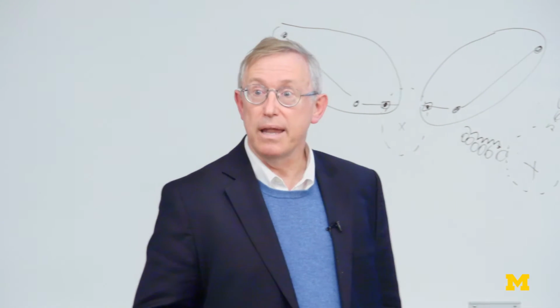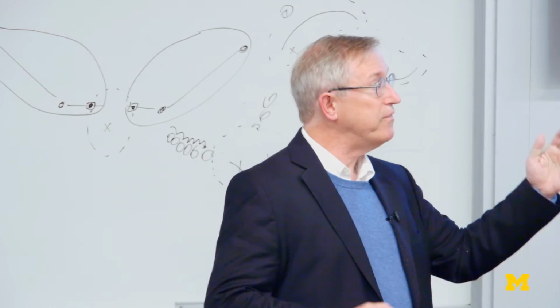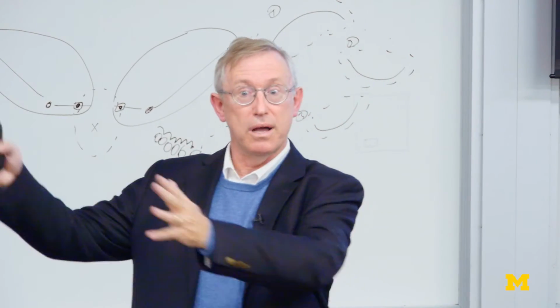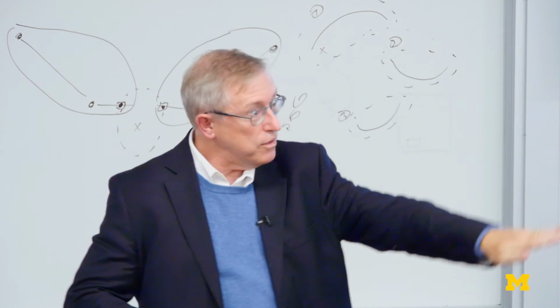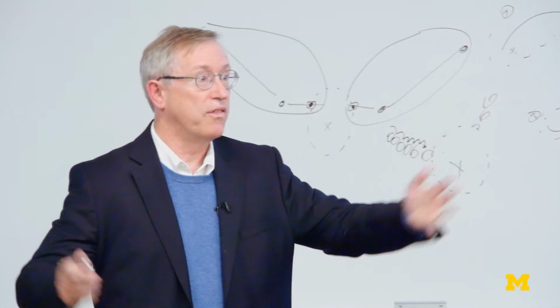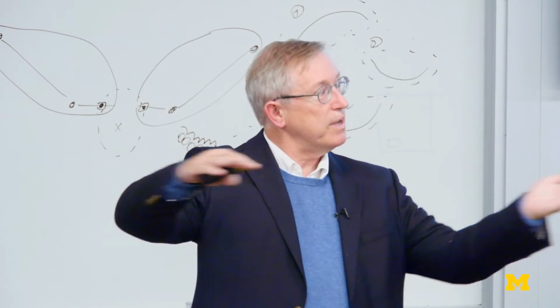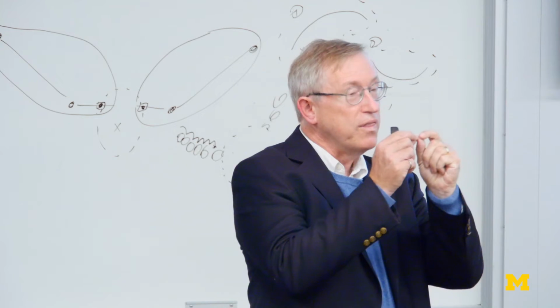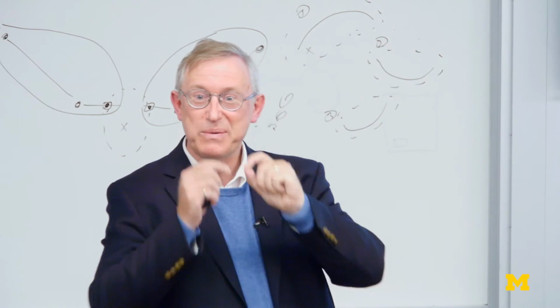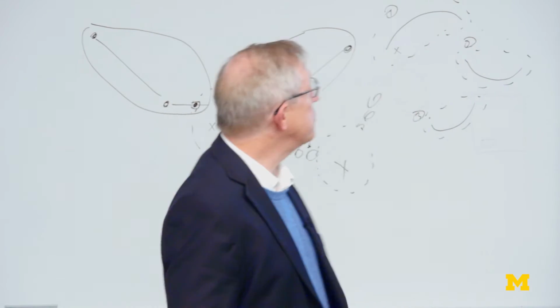That's not the industry standard. The industry standard is to do lumped amplification with so-called erbium doped fiber amplifiers every 60 to 80 kilometers along a link. So the signal decays in magnitude and then gets amplified and then decays in a periodic way along, say, a 1,000 or 2,000 kilometer transmission path. That's not what we're going to think about. We're going to think about this perfect distributed amplification system, or we can think about an infinitesimal spacing between lumped amplifiers. That's the idea. And this tends to give us better performance than the lumped strategy.